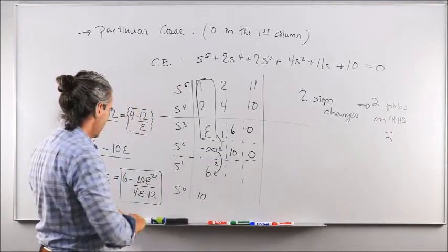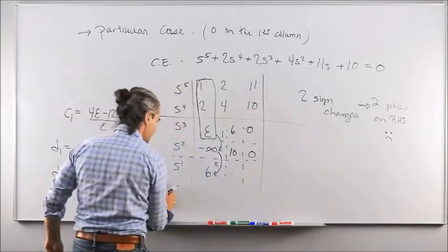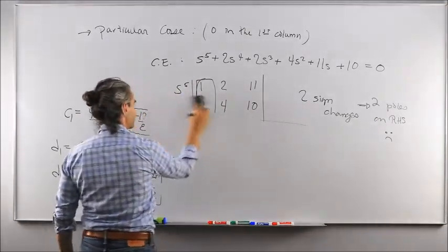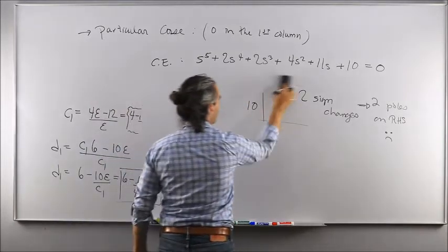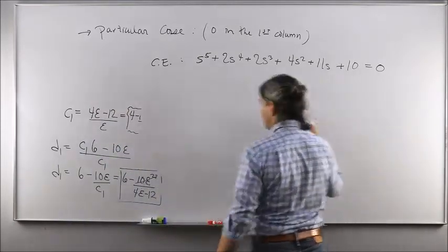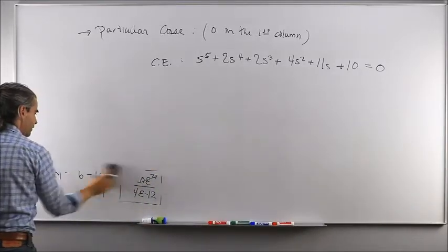So let's use this very generic linear feedback control theory, and let's apply that to, again, our particular situation where we are controlling the rotational motion of the spacecraft about a single axis using our faithful modified PD controller.